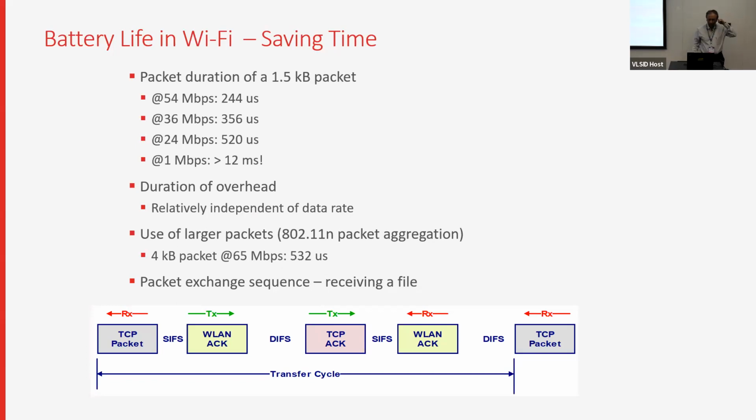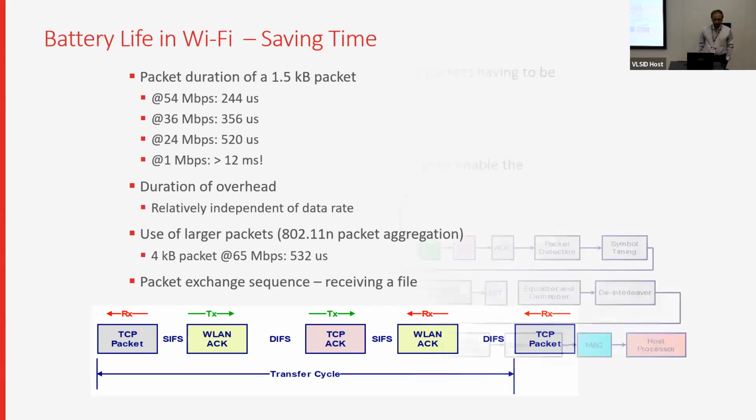We also do that. When somebody doesn't hear what we are saying, we try speaking louder or we try speaking slower, so that now maybe he can understand it properly. So the system also does the same thing. Now, if I am a little bit deaf, I will unnecessarily make you speak slower. So can a system receiver be made a higher performance receiver, so that even with a lower SNR, you can still get a better data rate? And that is where wireless system designers spend a lot of time and effort optimizing, right?